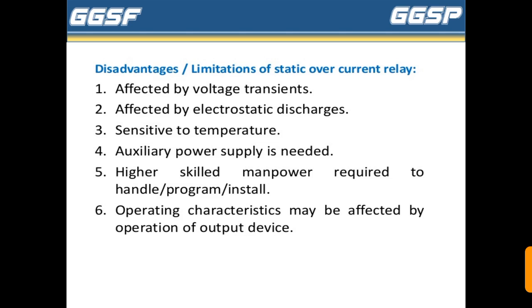Now some disadvantages and limitations of static over current relays are: affected by voltage transients, affected by electrostatic discharges, sensitive to temperature, auxiliary power supply is needed, higher skilled manpower required to handle, program or install, and operating characteristics may be affected by operation of output device.